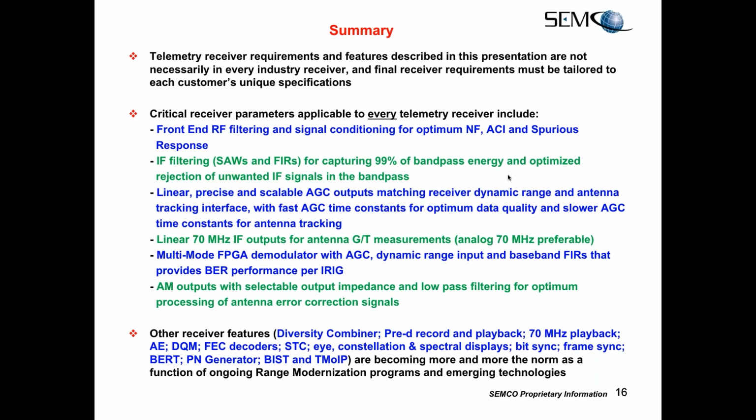First one is in regards to your power supplies, the dual redundant power supplies. Are they hot swappable? And follow up, what notification do you get when a power supply goes down? Well, the answer is yes, they are hot swappable, and you get both an audio and a visual indication. The power on off light on the front panel begins flashing, and you hear an audible tone that you can reset on the power supply. If you want to continue running the receiver on one power supply, you can reset the audio so it doesn't become an irritation. But the power on off light will continue to flicker until such time as you replace the defective power supply.